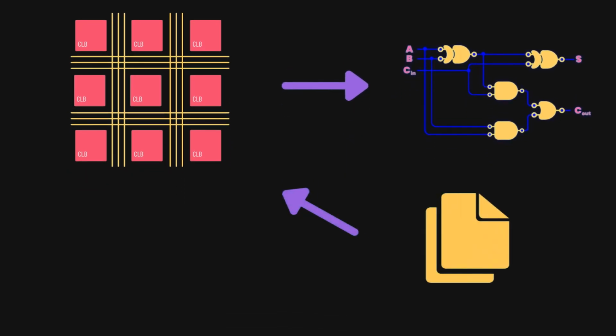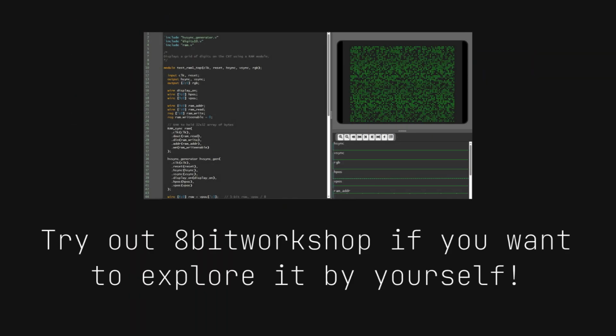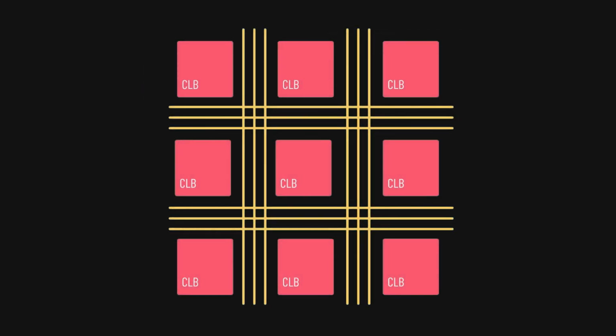You define some digital circuit using a hardware description language, or HDL, run that through a synthesizer and upload to the FPGA. That FPGA will then act as the circuit you created. It is very important to emphasize that the FPGA isn't just simulating the circuit. It actually is the circuit. Their wires and gates are all actually there, working together all at the same time.